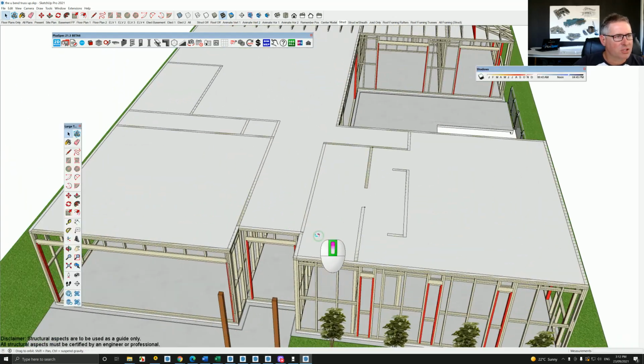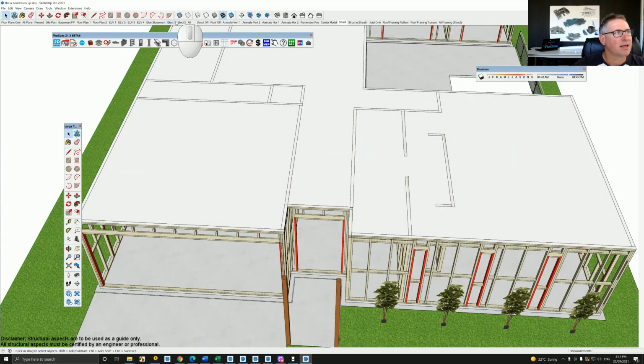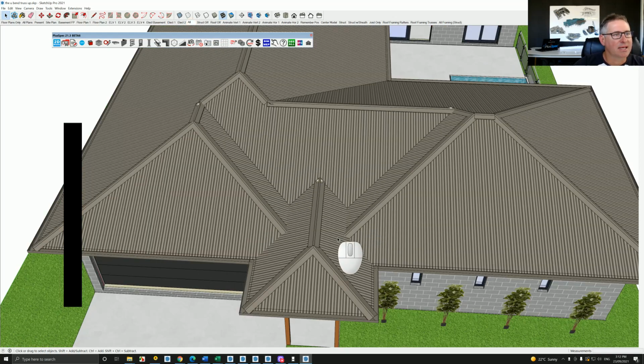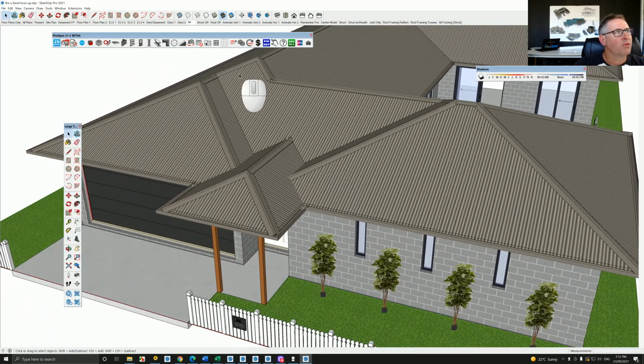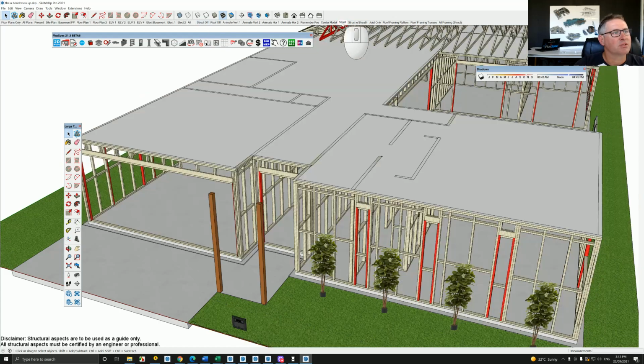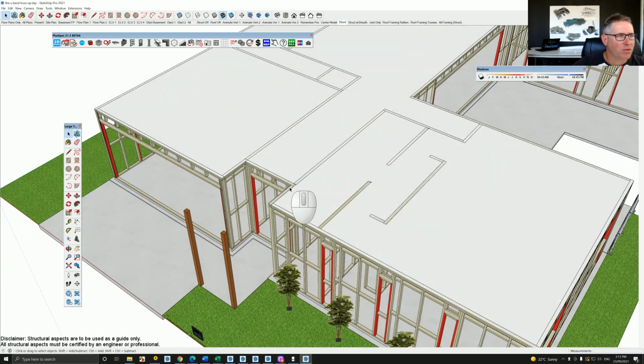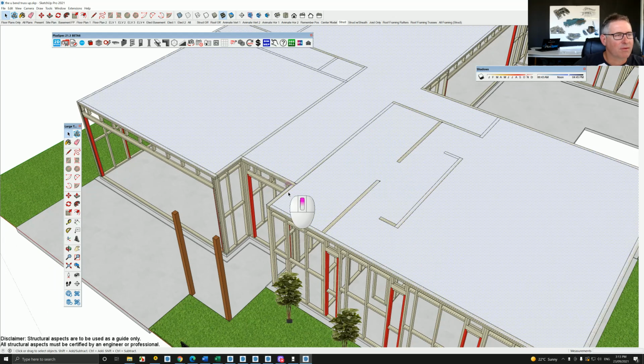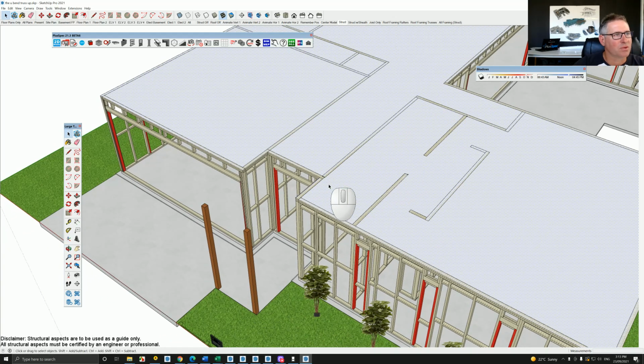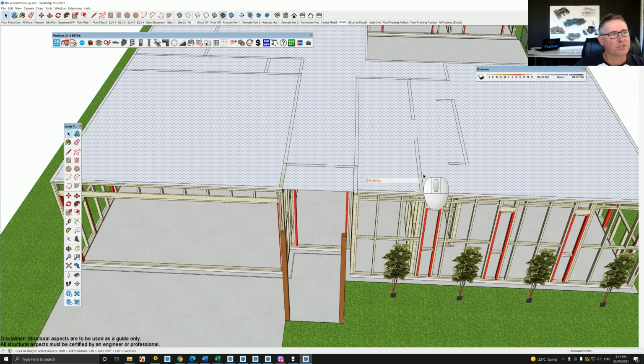The first issue is, and the reason why the roof has this indent is because when the roof's been created, go back to my structure scene, the face has been created from walls. However, you can create a face with the rectangle tool, and I'll give you an example. A rectangle, and I'll basically go from here to here, and it will actually create a rectangle. That gave me two different faces. Now if I wanted to get rid of the difference between the face here, I can just push delete, and then I have one solid face.